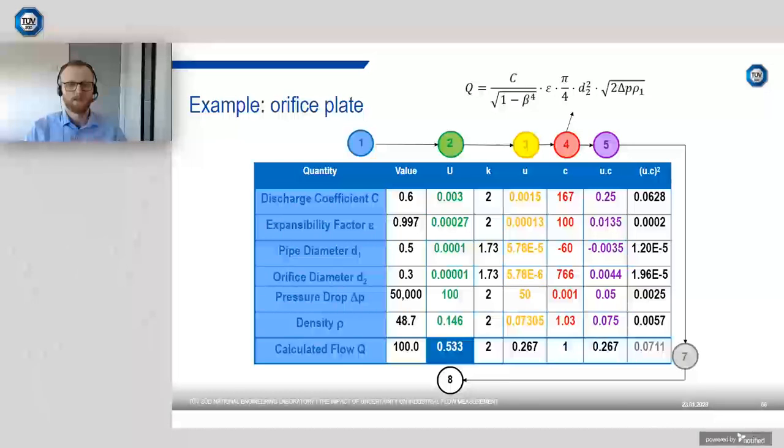The result of this is that the standard uncertainty calculated is a bit higher as opposed to dividing by 2. But that makes sense because we are essentially less certain where the true value would lie. If the frequency of readings was more around the middle, around the average of the points, we'd have greater certainty. So that's why we divide by 2 for the normal distribution as opposed to 1.73 for the rectangular, which gives a higher value, because there's a greater chance that you may be at the extremes of these limits.